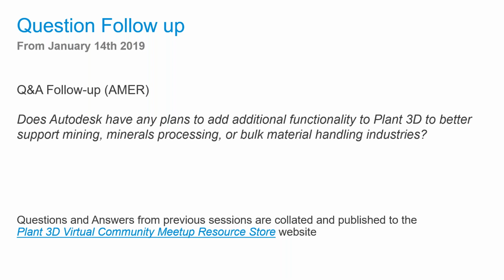Did you have something? Yeah, we have a question asking about the autosave command. The question is, when we first started with Plant 3D, we were told not to use the autosave command because of conflicts with writing to the SQL database. Is that not an issue? I haven't seen anything reported around it. There's two things, the autosave and then there's a save percentage, right? It gets pretty complex around that topic. So we'll see if we can find some information on that. I think it's okay to use it.